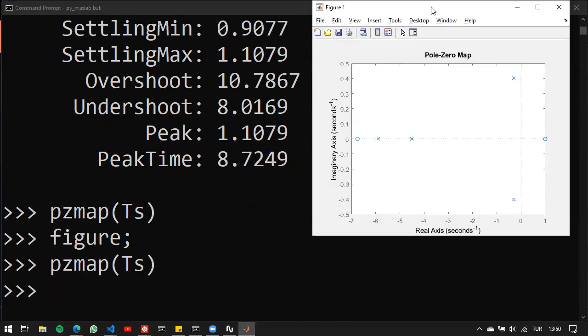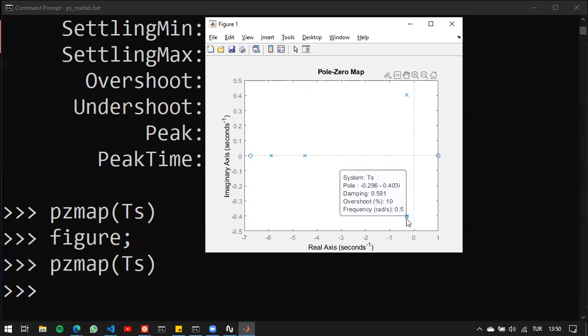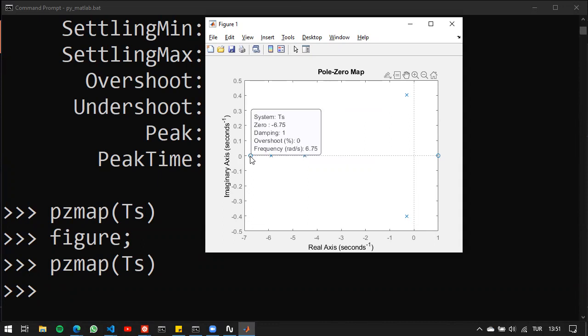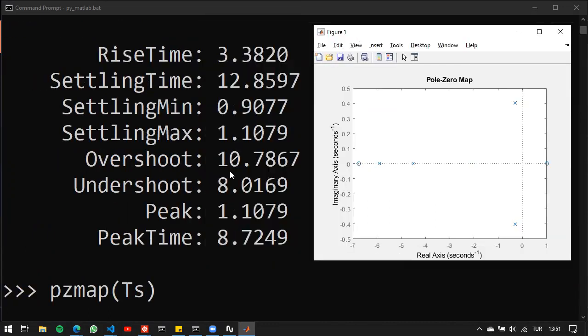Let's look at the pole zero map. We have a 0 on the right half plane. That's already because of the approximation. We have 2 poles here, and one of the poles is at -4, at -5, and then we have a 0 here. Of course, we should use tabulation or, as again mentioned, the root locus method in order to optimize the dominance factor. But yeah, I've skipped that part for now. We can see that this is technically something that we can use because it has the overshoot value that we are interested in, and it has a certain settling time value. We didn't really limit that.